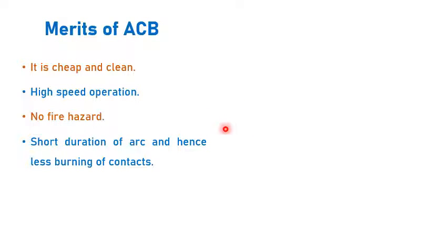And in air blast circuit breakers, the duration of the arc is very small. The arc will be quenched in a very short time. Therefore the arc cannot burn the moving and fixed contacts. It's also used for frequent operations. Frequently you can switch these circuit breakers on and off, so there is no burning of contacts.